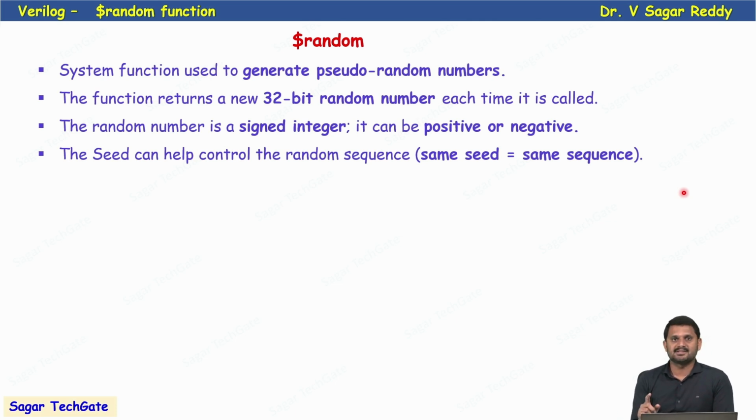It is not synthesizable. Remember, we use $random only in the test bench, not for design purposes. That means it can only be used in simulation, not in a real hardware design.